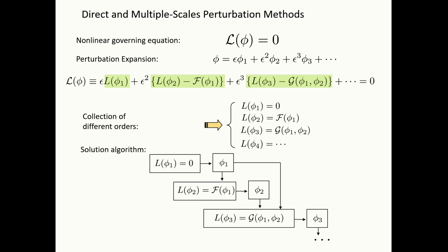So typically, if we want to use approximate analytical methods, the perturbation method is very useful and handy. If I denote the entire set of equations by this nonlinear operator L acting on velocity potential phi, then we assume that the velocity potential can be expressed in terms of a perturbation series. It's an assumption. If that's correct, we put it back there. We get a bunch of equations that can be solved sequentially to give us the first order, and then correction, and so on.